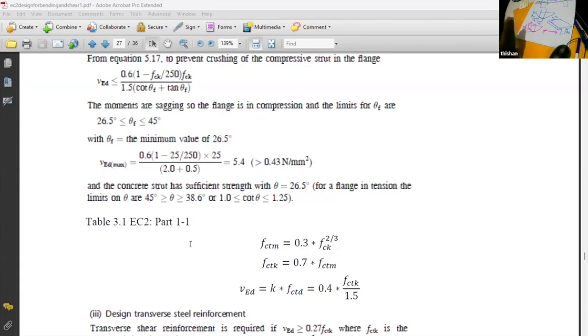That is a common area, and if it is going to fail, the stress should be large enough. Here the stress is so small that it's not going to fail even if you don't provide any reinforcement. That's what you generally find.